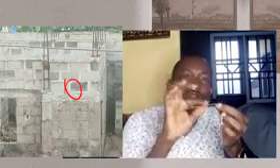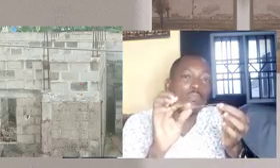Now if the person in charge of this is not an engineer, there is every possibility that at the beam top, for the slab, the reinforcement there is still likely to be just two bars, instead of making provision for the upper one to be more than the lower one.